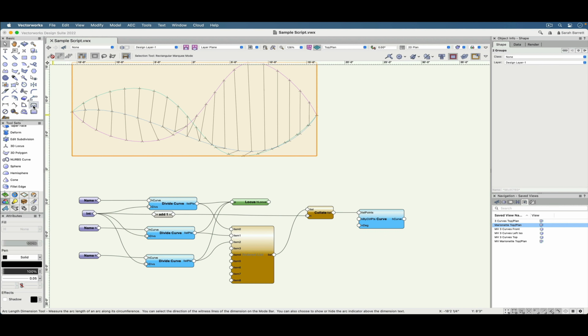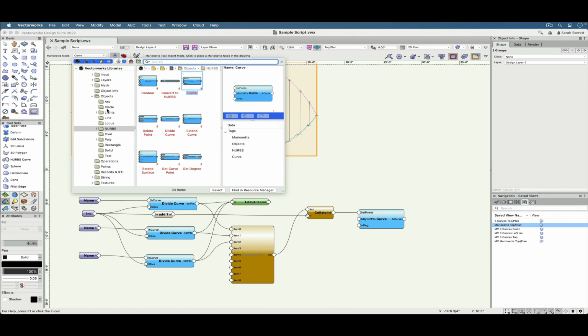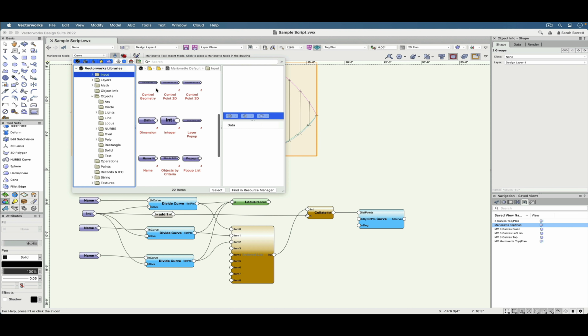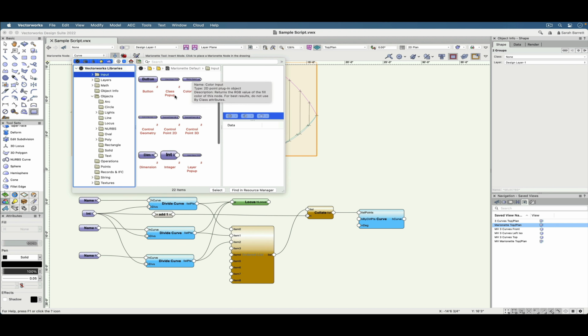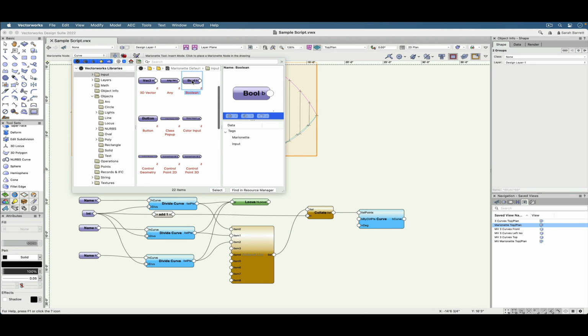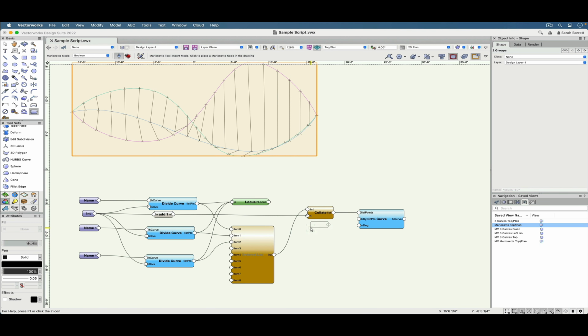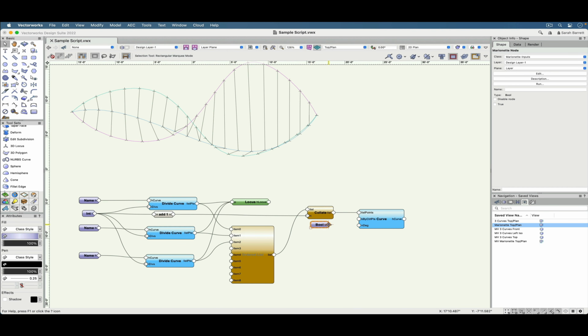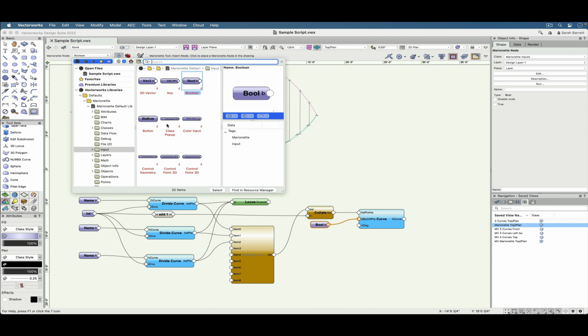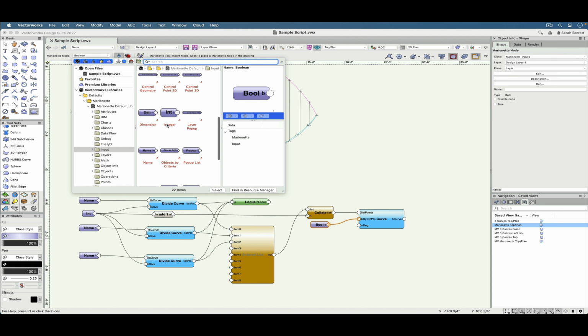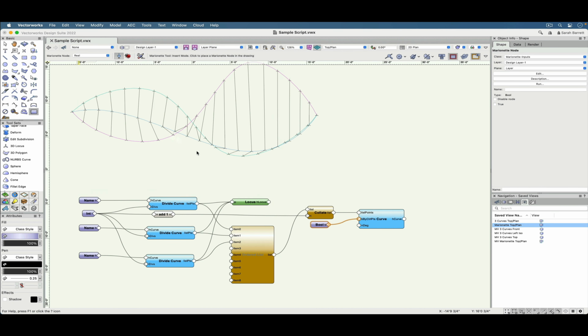The two nodes I need for the inputs are a Boolean node and a real node. The term Boolean in coding is meant to represent an either-or value and is most often defined as true or false. The Boolean node allows you to choose between two options. In this case, it's a choice of by control points or not by control points. The default value for the Boolean node is false, so I will leave it as it is.